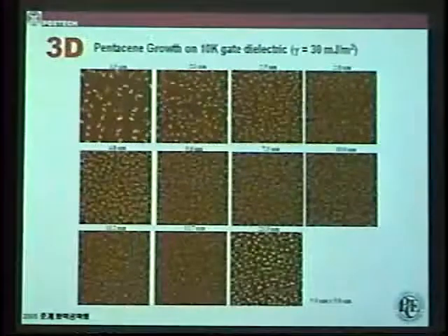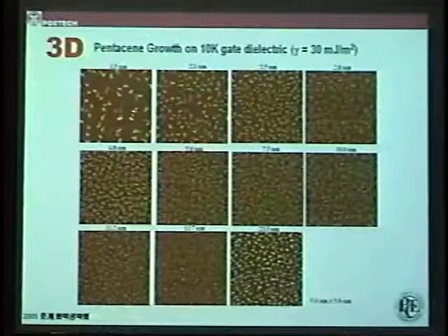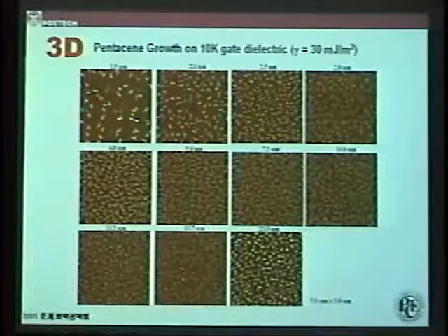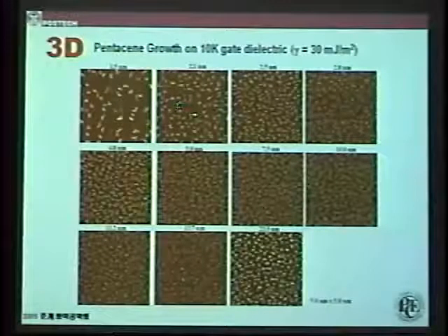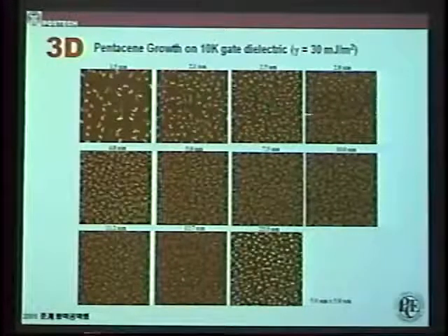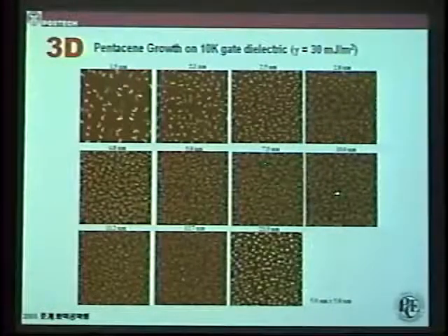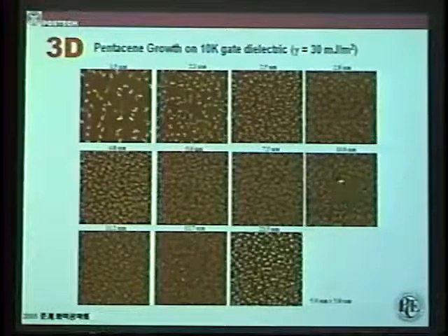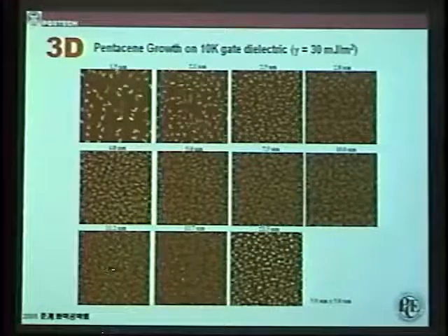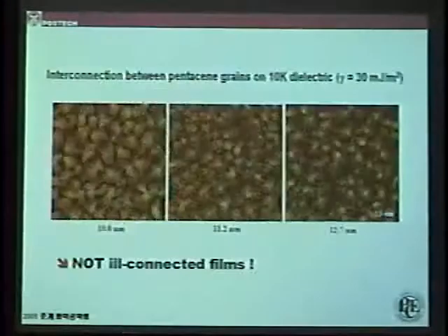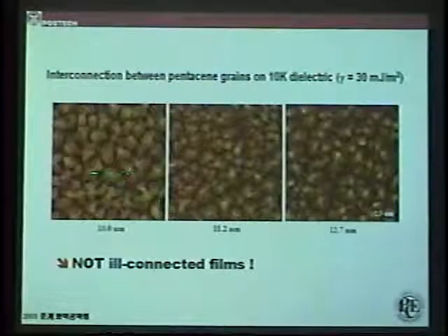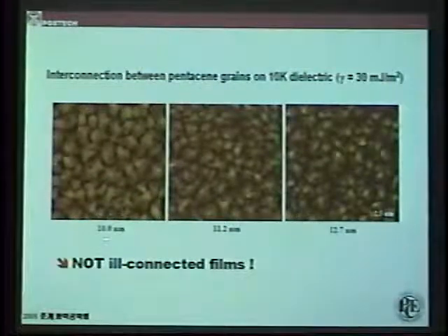And in the case of low surface energy, we have a first layer with most of it bare, and the nucleation is further in the bare space. Then at about 10 nanometers we have a kind of web connected structure, and for the cross packing, at about this thickness we have this kind of morphology. This is a higher magnification of the previous slide. At about 10 nanometers we actually find an increase of mobility, as the grains are interconnected with each other.